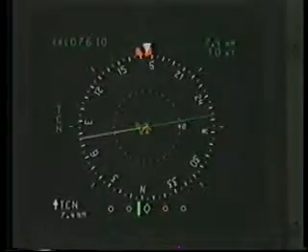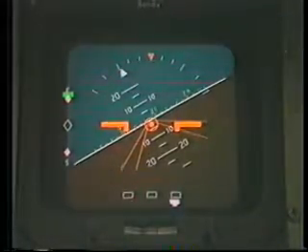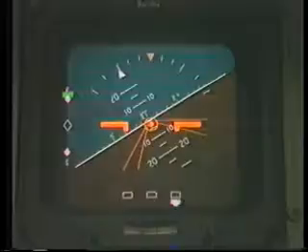Press the range knobs to vary the scale, like this, and notice the aid symbol disappears with the 2.5 mile scale. Also notice the ground speed, because we are now abeam the station. Now for a right turn. During the turn, select the Melbourne VOR and pull the course knob. We're on the 032 radial from Melbourne. The VOR has a co-located DME station so the ground speed works.